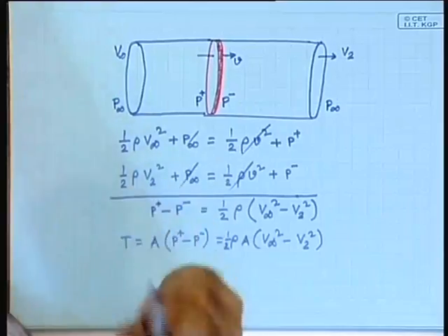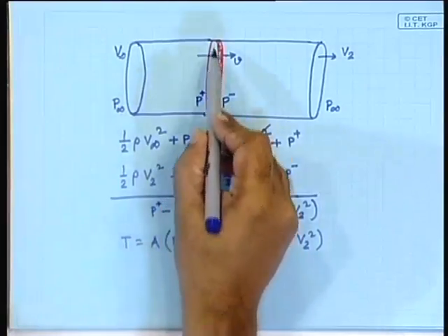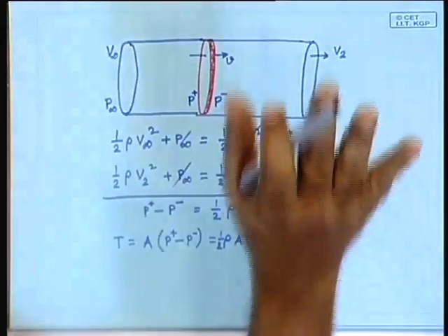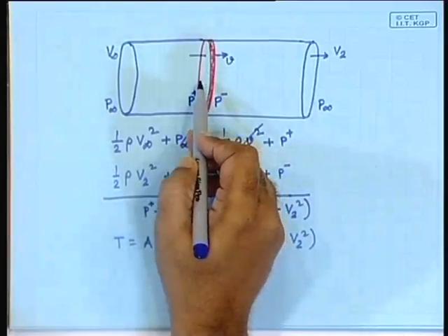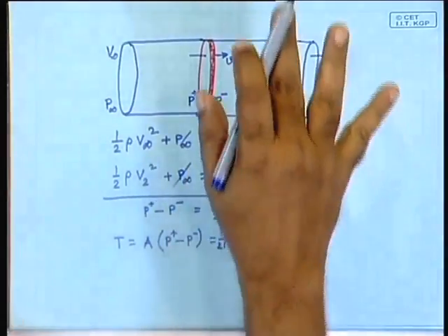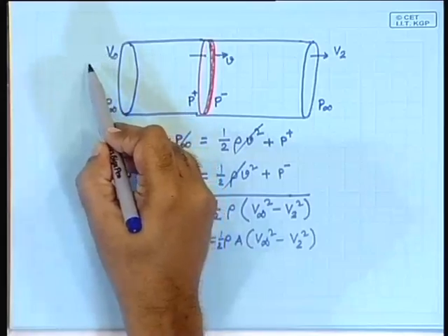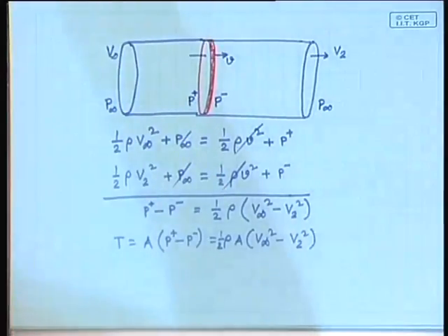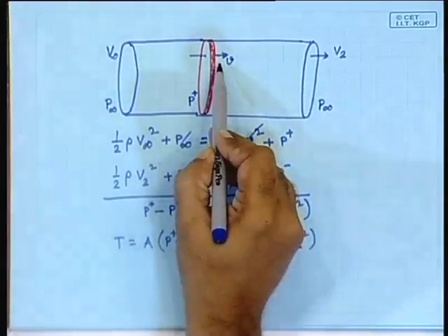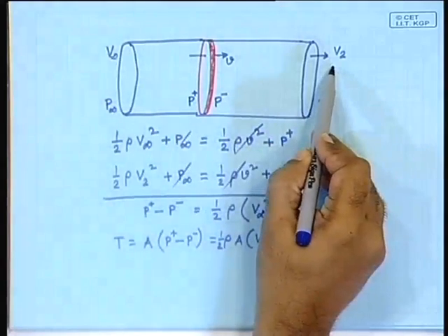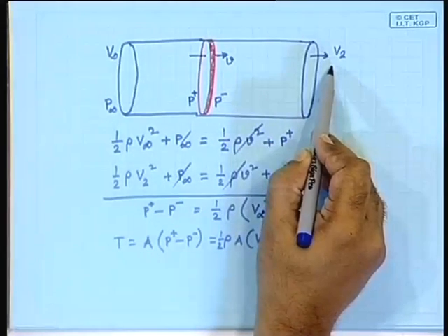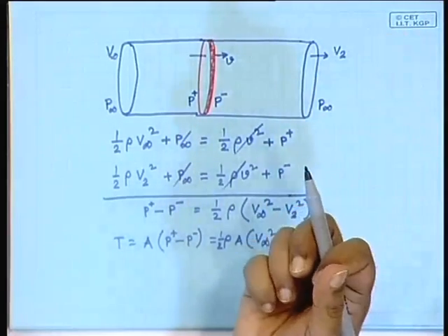And the maximum depends on what this fellow is doing. Imagine the two extremes. This fellow allows the air through without any hindrance. As a result, your V is equal to V infinity and V2 is also equal to that. In that case, how much is the power extracted?